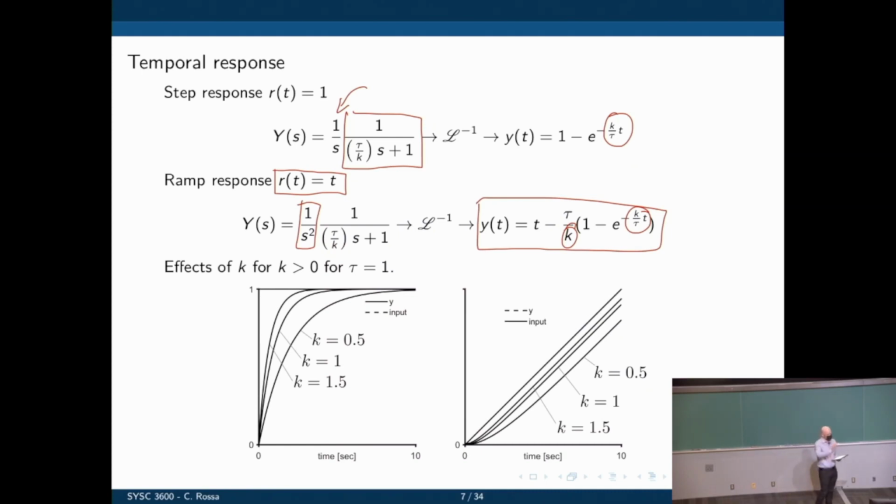So now let's take these two expressions and plot them. We did this in the past lectures. The only difference is now we have control over the time response. Before it was fixed, it was part of the plant. Now we are controlling the plant using a gain. And we see that we can now change how fast the system responds by controlling that gain. We see what happens here as K is increased. The time response indeed decreases, the system reacts faster. That's for the step. And for the ramp, you see the transient there getting smaller and smaller as K is increased.